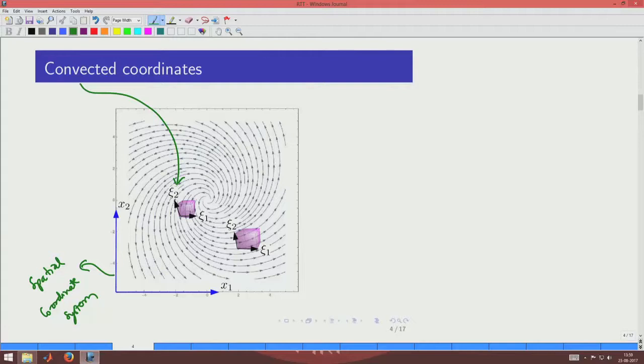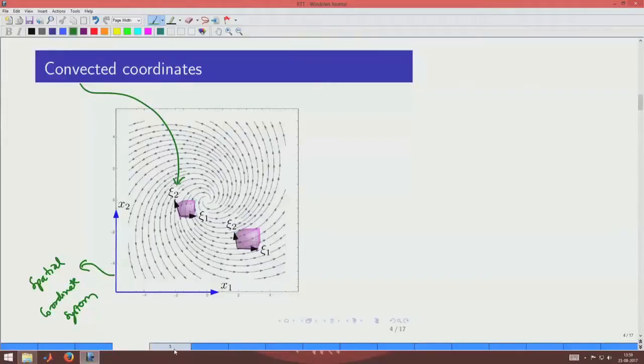Now, this is a little different from the transformation of coordinate systems we discussed at the beginning of this course, where we said that the coordinate system is having a pure rotation. So, here it is not just pure rotation, we also have dilation introduced, and that is why we cannot use those expressions directly, but there is some parallel in situations where the volume change of the control volume as it is moving around happens to be 0. So, if the volume change is not there, then we could use the same expressions, but in the general situation we should not.